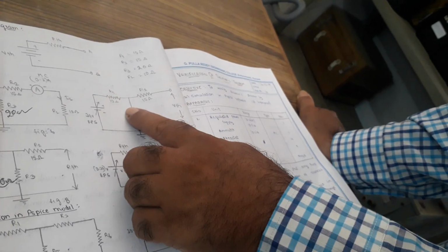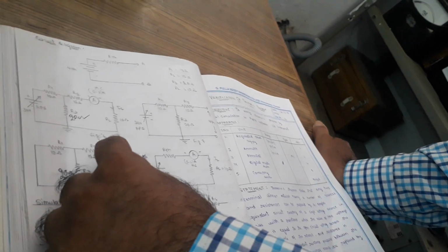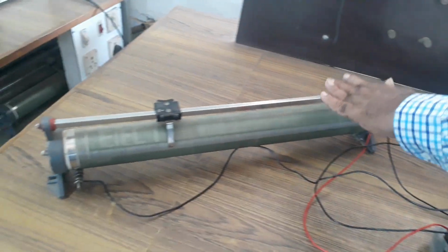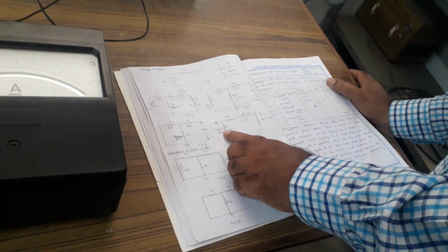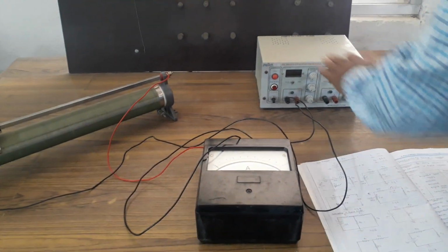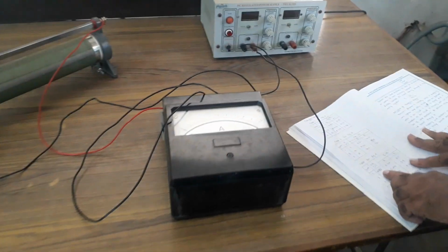This can be calculated as R1 and R2 connected in parallel, then connected in series with 15 ohms, and then we get RTH across the open circuit terminals. We place the calculated RTH value, 21.66, and connect the final equivalent circuit with RTH in series with VTH. From the RPS to the RTH, from RTH to the ammeter, and to the negative terminal. Here we are applying only VTH, not the RPS supply voltage. That is the Thevenin's voltage.